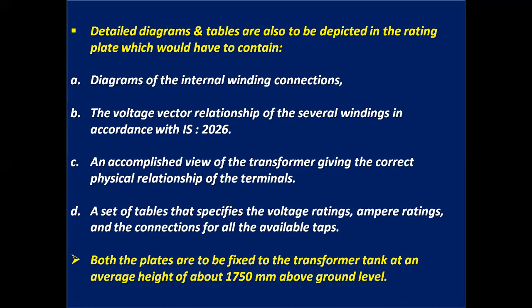Both the plates are to be fixed to the transformer tank at an average height of about 1750 millimeter above the ground level.